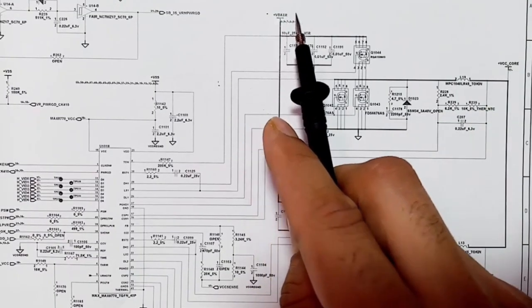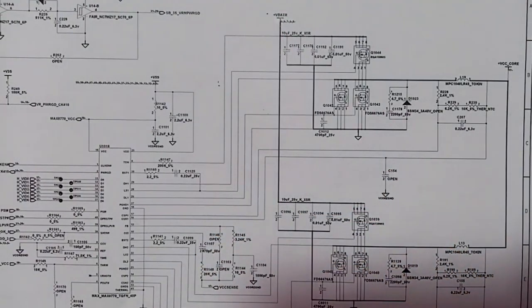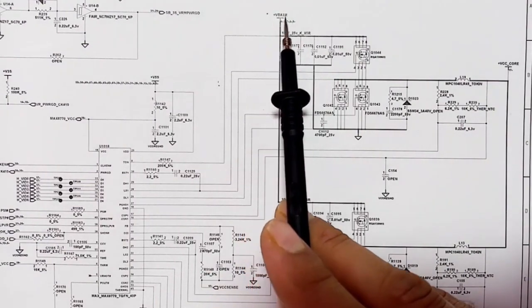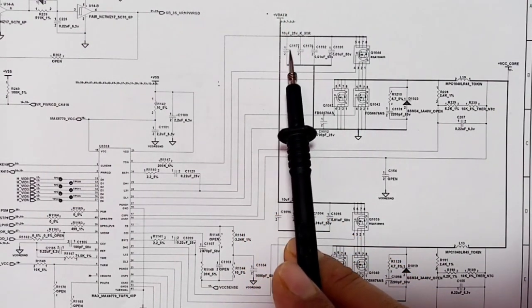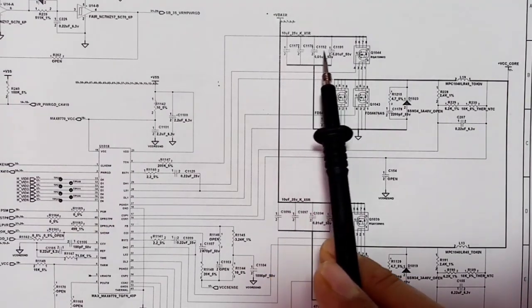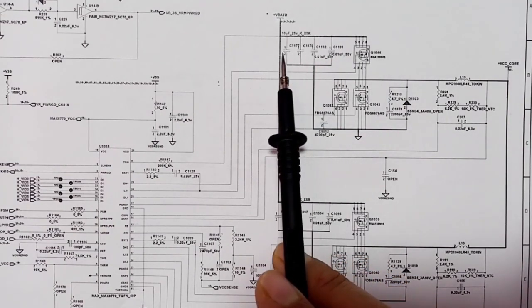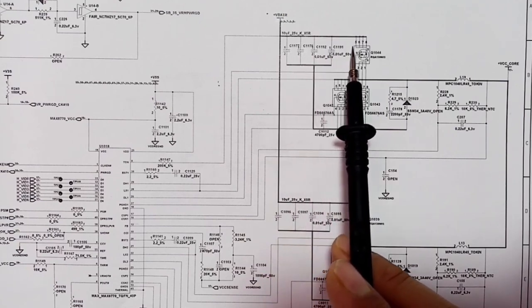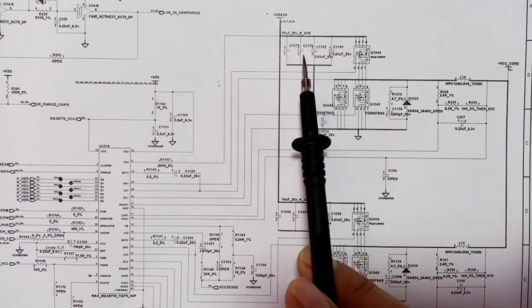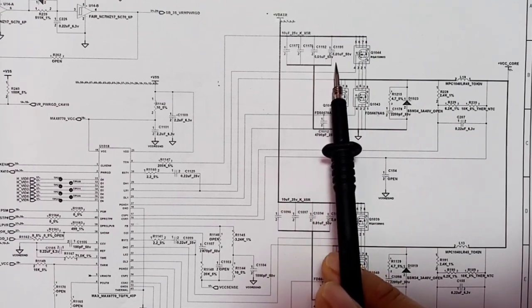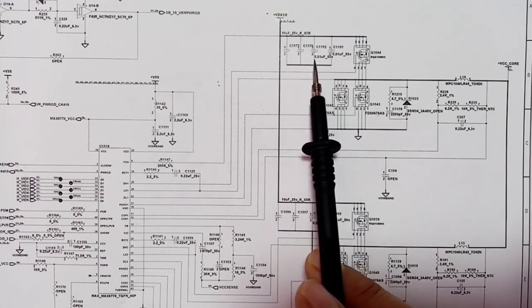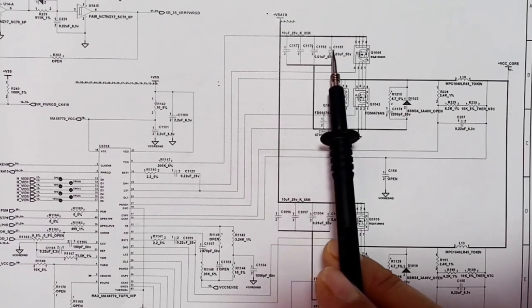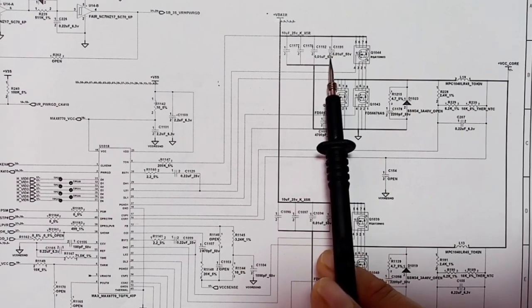So this is basically the input voltage for every circuit in the motherboard, including the CPU circuit. We have plus VBAT, which will be applied through these ceramic capacitors. We have here 4 ceramic capacitors: C1177, C1176, and so on. All these ceramic capacitors have the same capacity and the same voltage: 0.01 microfarad, and the maximum voltage for these ceramic capacitors is 50 volts.